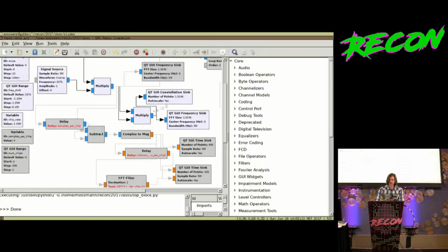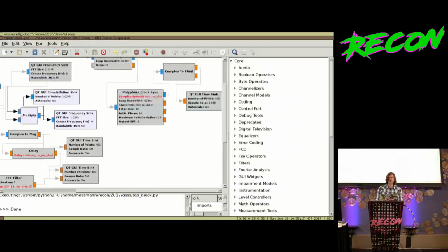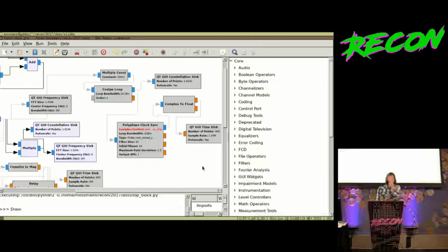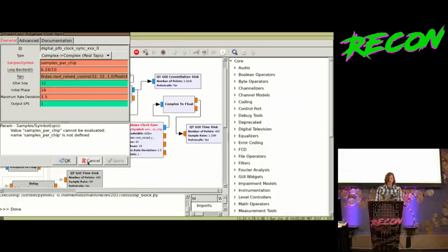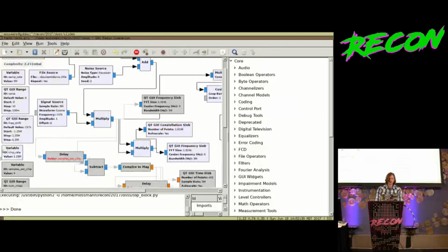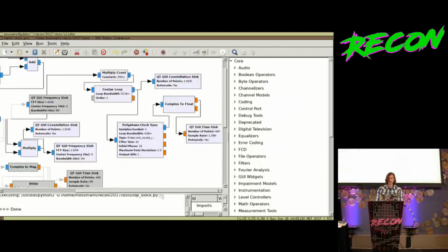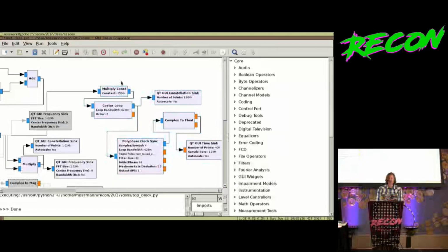And I'm going to show you another trick. Actually, before I show you another trick, let me show you the traditional way to reverse engineer this at this point, and I think this is what Kobe Moore did. He used a BPSK demodulator here. He needs to know the samples per chip, which is computed here from the chip rate and the sample rate. And now I can take this and just demodulate it.